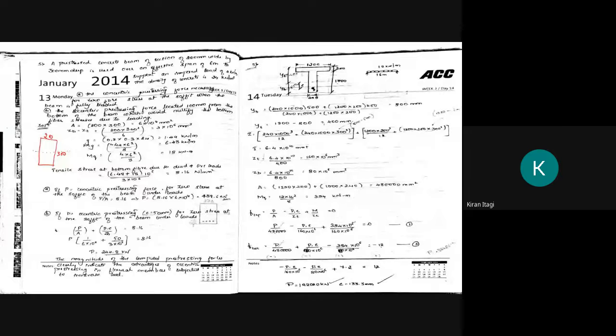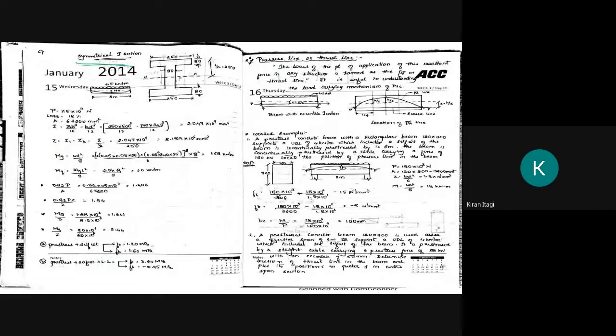So here we can see the pre-stressing force for the concentric and the eccentric cases. The magnitude of the computed pre-stressing force clearly indicates the advantage of eccentric prestressing in a flexural member subjected to transverse loading. So it is better to provide the prestressing force at a certain eccentricity rather than concentric, to nullify the tension in the concrete members. You can solve the same thing as homework. Next, we will see a symmetric I section.